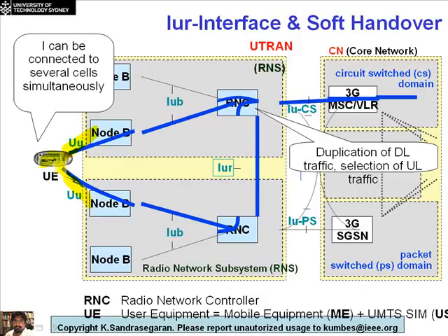In the uplink, the data that it's transmitting goes to this node B, and it also goes to this node B. And from this node B, it goes to the appropriate RNC, and then the RNC looks at the data that's coming through, and it knows that this particular connection is associated with another RNC, and it sends this data along the IUR interface.